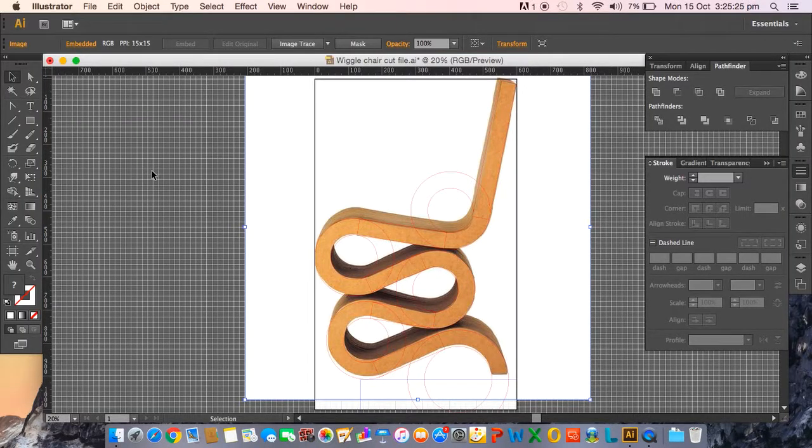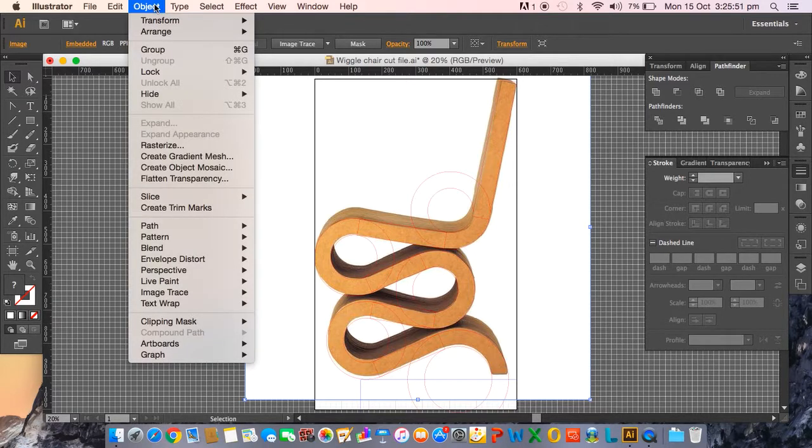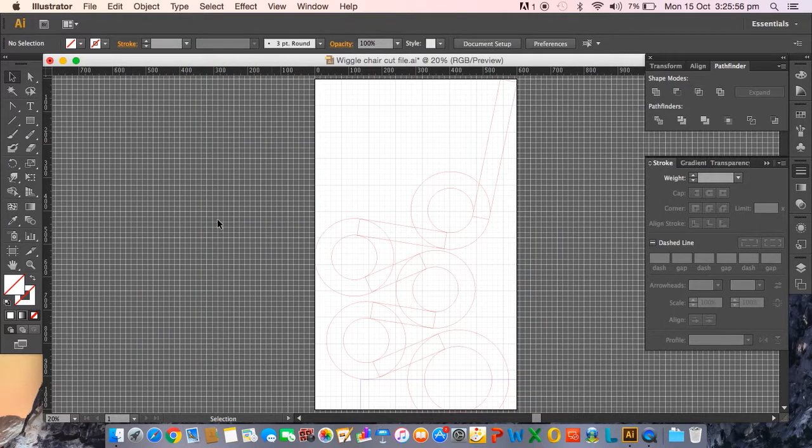So when it comes to building much more complex shapes, take for example the exact replica of the Frank Gehry wiggle chair, you might want to use your drawing or, like I've done here, cheating really, an image of the chair that you're trying to design in the background. You can copy and paste that in as long as that's a JPEG. When it's selected, you can go up to Object and hide the selection, or Control 3, and that means that it disappears, and you can continually bring it on and turn it off so that you can build up your shape.